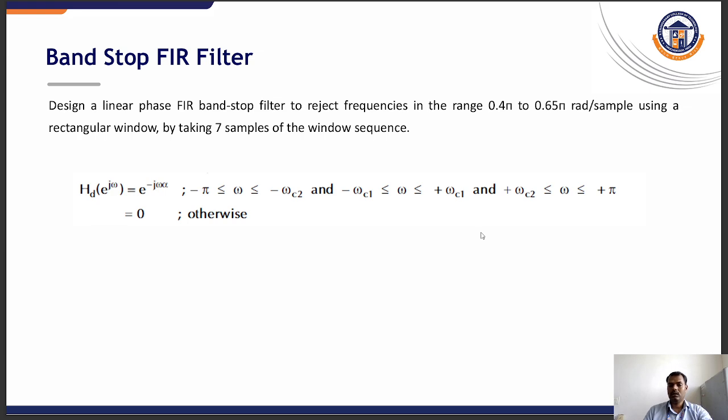But the significant drawback in FIR is that it often requires a much higher order, that is, a large number of filter coefficients, to achieve sharp frequency domain specifications as an IIR filter does. This makes them more computationally intensive and it can introduce longer delay, which may be a concern in real-time applications. So the most common methods of designing FIR filters are the window method and the frequency sampling method.